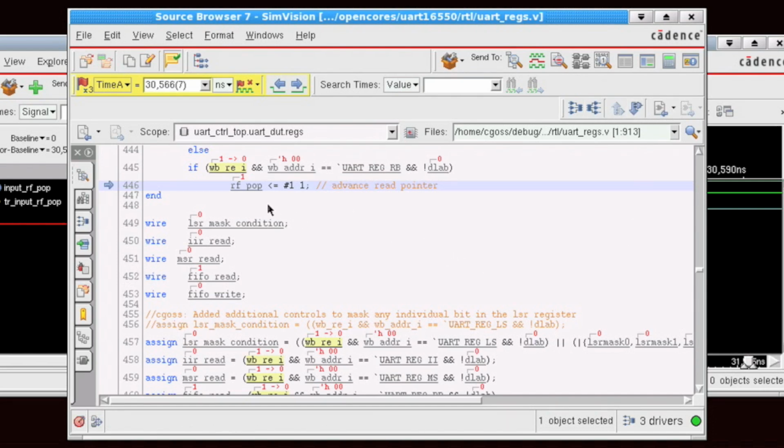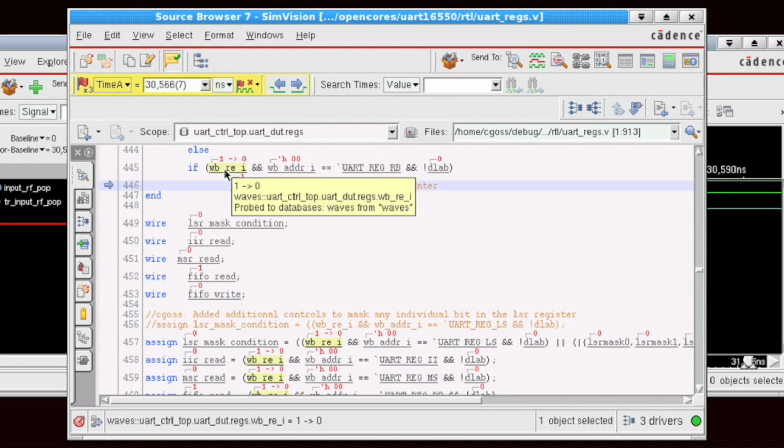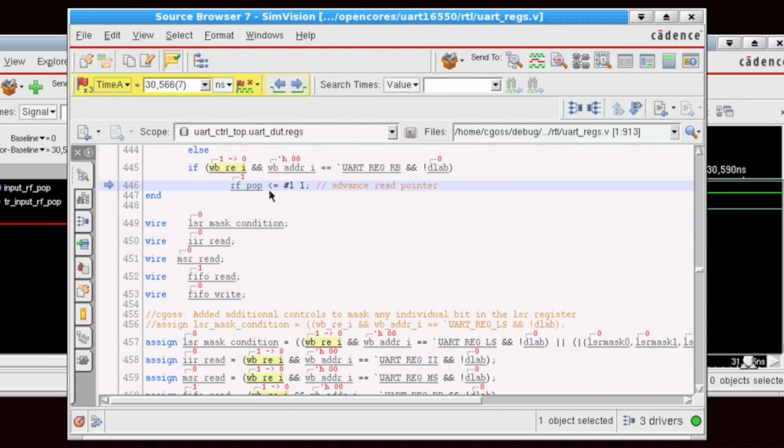Now, for any driver that's selected, there's a number of contributors that cause that driver to be selected. And in this case, we see that there's 3 in the if statement above. One of them is highlighted. The reason it's highlighted is because this is the most likely contributor that's causing this driver to be selected, and you'll see that it's the only one that's transitioning right now. It's an indication to the user that this is where you might want to continue your driver tracing operation next.